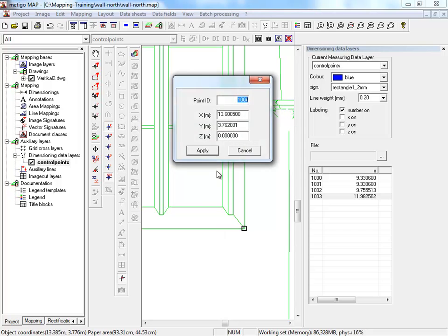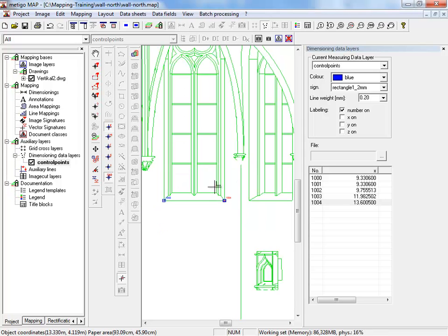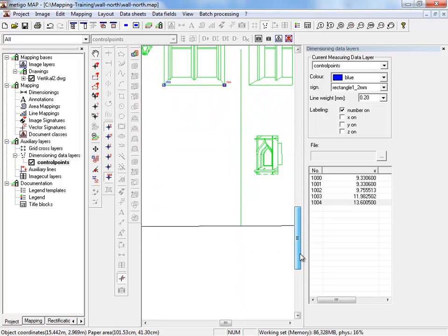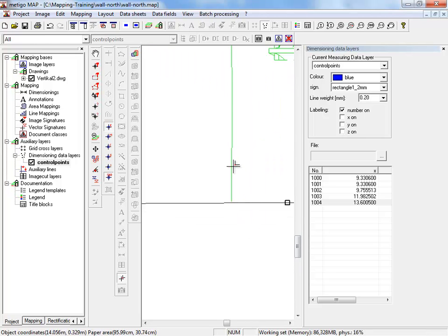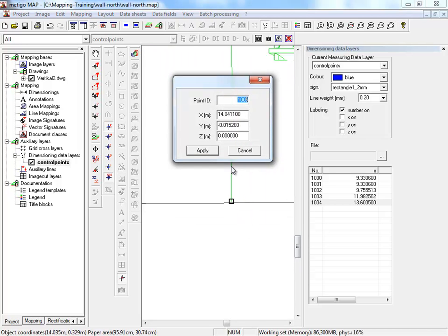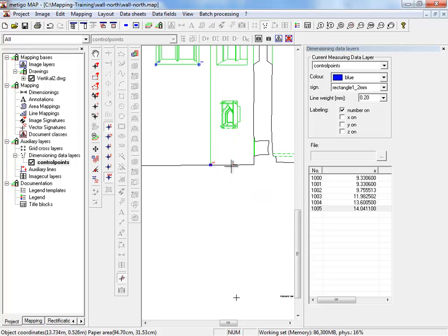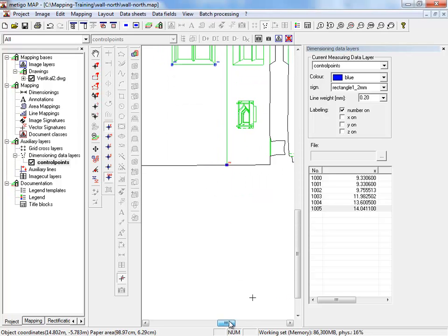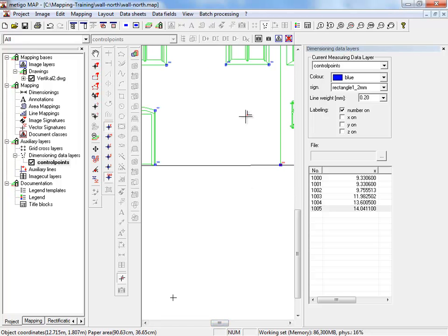You need at least 4 points for the image rectification as a minimum. Better are 5 or 6 reference points for the software to calculate the residual error for every point. With 4 points you have no error checking. So we have started with these points for the rectification of the first image.